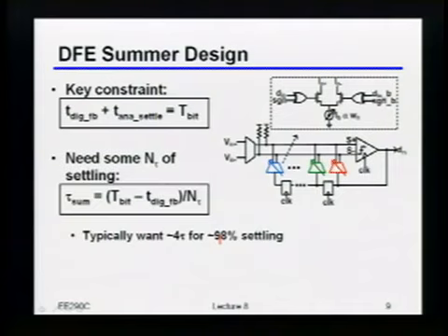Okay? So now, just to make sure that everybody gets why this is important here, let's say I was really talking about a 10 gigabit per second system. What does that mean the tau of this summation needs to be, approximately? What might be your digital feedback delay? Roughly speaking, let's say in a 65 nanometer technology. I heard somebody say it, just speak up. 8 pico? Okay, yeah, probably about 20 to 30 picoseconds. So let's call it 30 picoseconds.